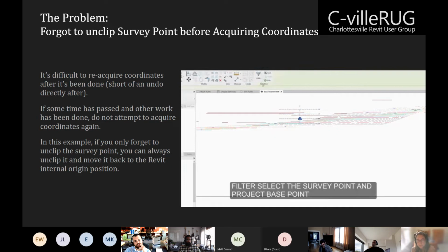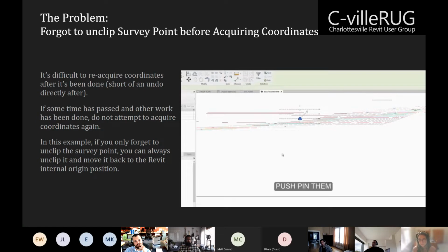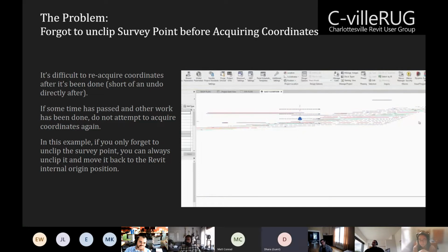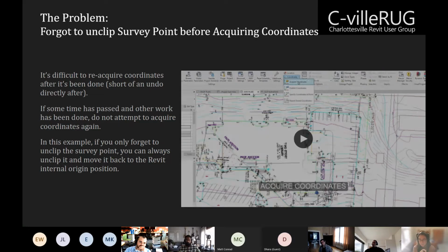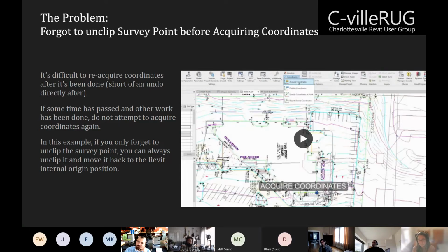The big difference is that if you put the corner of your building at the origin, when you set up the separate site file in Revit and link in the AutoCAD file, you'll be able to find the building footprint in the civil survey, find that same corner, and put it at the origin.